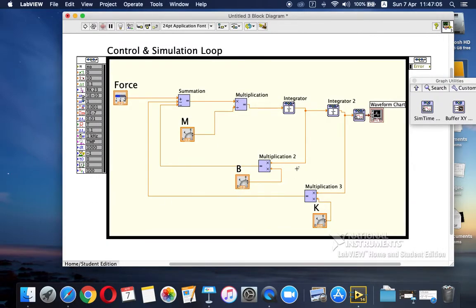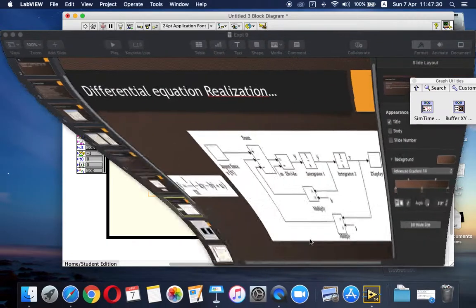At each stage of the input, you can see what the output is, how the velocity changes, how the acceleration changes. This is called a distributed parameter model. That's called a lumped model, where you have a transfer function for direct working. This is called a distributed parameter model, where you can vary each and every effect M, B, K, and we can see what the effect of each is, how the poles change, how it affects the system. All those dynamics can be easily studied.